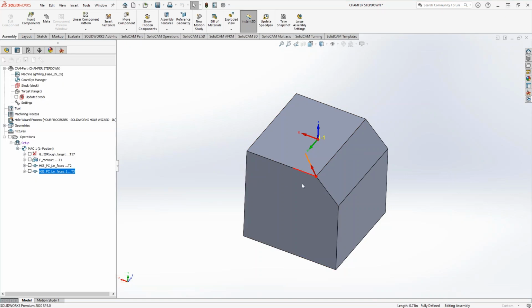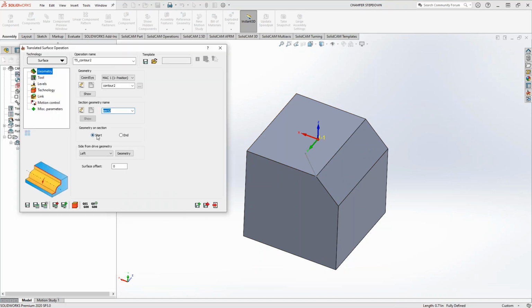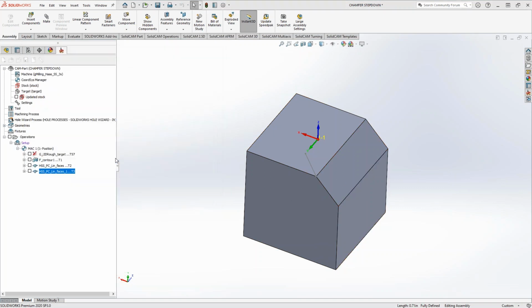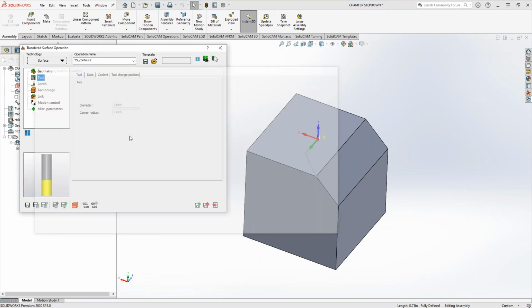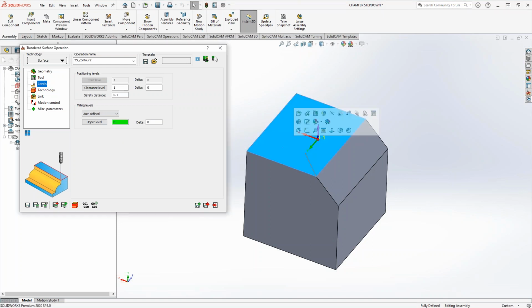So again, it kind of doesn't make sense when you look at the path and that, but again, lower left corner, lower right quadrant of the toolpath. And then I believe I needed to put this on the right side, because in this path, I need it to be on the right side. Let's just choose a tool. So I'll go with my 1-inch roughing tool, levels. I'll just click on the top of there.